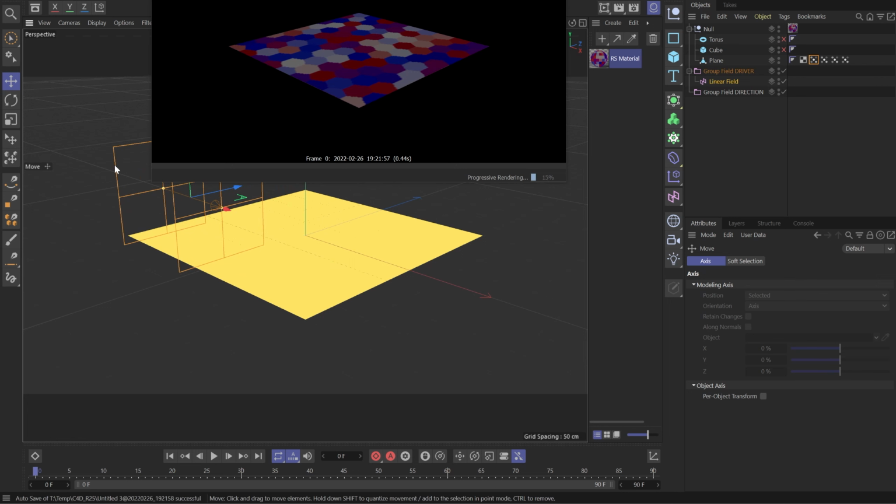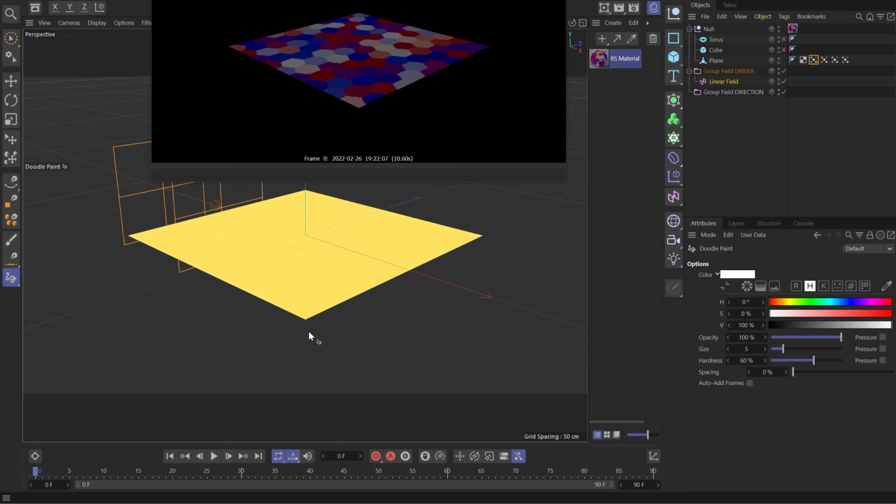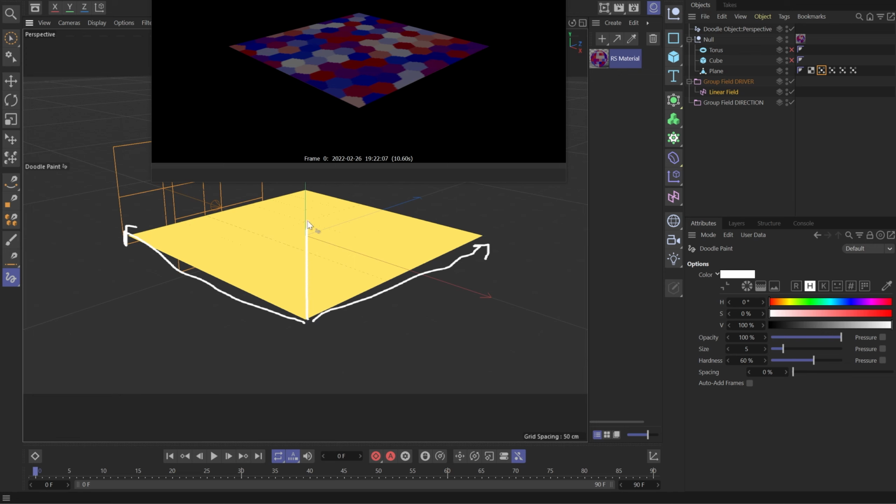And you see, when this linear field comes from a straight line and it's fully covered with yellow, we don't see the top layer. That's because our setup moves UV map by the length of 1, which means by the length of this square segment. If I move my UV map by the length of 1 in the X or Y direction, I can fully uncover the base layer. But if we move from that point to that point, we have to build half of a circle here, and our setup will move our UV map only till this point.